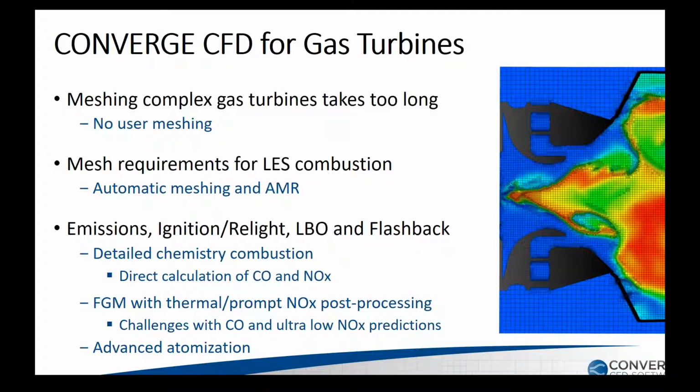Another key point is that mesh requirements are important for LES combustion. As I mentioned in that white paper, we talk about that. And adaptive mesh refinement and automatic meshing really do give an advantage of being able to resolve the flame front such that detailed chemistry can be accurately applied.